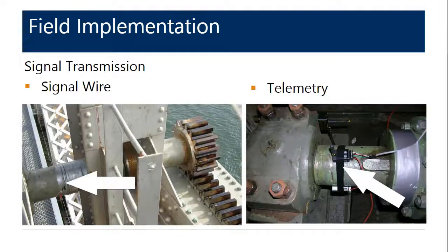With the gauges installed in the Wheatstone bridge configuration that Adam previously described, the circuit is directly wired to a data acquisition system that provides an excitation voltage to the circuit and conditions the signal to record calibrated shear strain. The photo on the left depicts a strain gauge installation directly wired to the data acquisition unit with the wire wrapping around the shaft during operation. The photo on the right depicts the strain gauge installation wired to a telemetry signal that is battery powered and rotates with the shaft. Either method of signal transmission is applicable for operational testing.